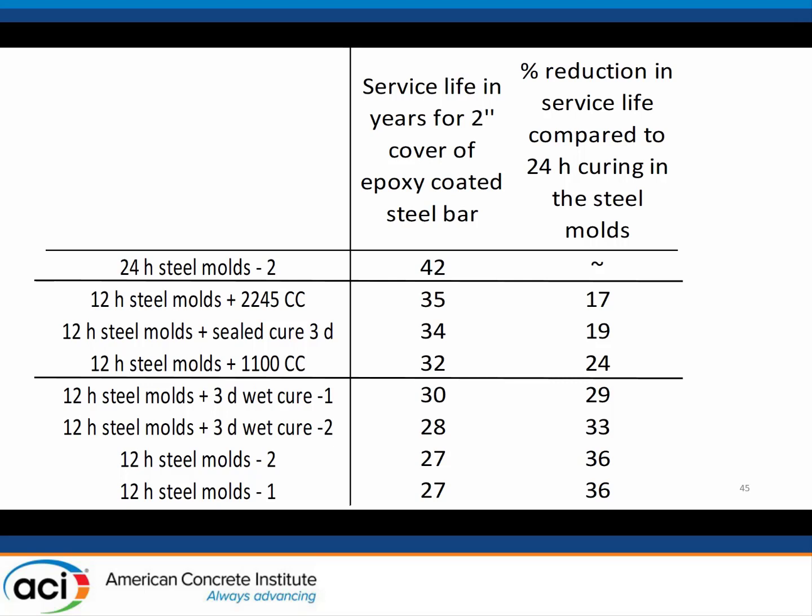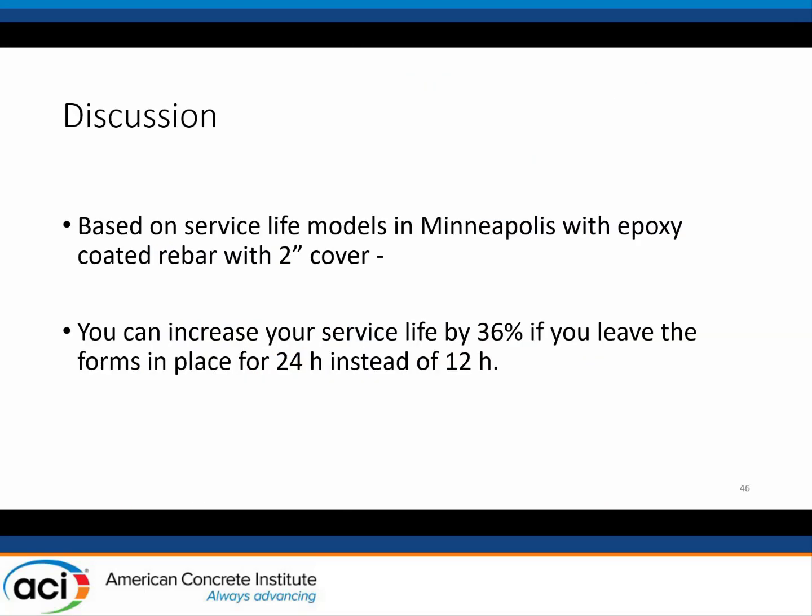Strip for 12 hours. The wet curing and just stripping the mold at 12 hours, you lose about 1/3 of the life of the structure. For chlorides with a 2-inch cover, epoxy-coated rebar in Minnesota. That may not be your project, that may not be what you're about. What that shows, though, is for certain people in certain locations, curing is extremely important. So based on the service life, there we go, you can increase your service life by about 36% if you leave the molds on for 24 versus 12. I get it. It's not constructible. It might not work for you, but that's what the numbers say.